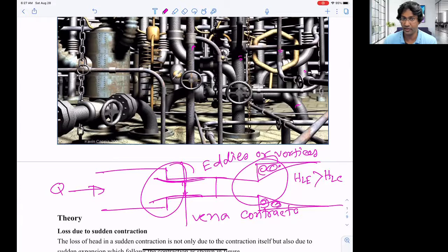due to friction, because you have to check if the flow is laminar or turbulent. Most of the pipe flow will be turbulent. So for turbulent flow, you have to know the material of the pipe, and from that you can check the table where, from research and different experiments, people have already found the exact roughness for literally every material. So you can use that value, the friction factor f, in order to calculate your major loss. So you can consider only your major loss, right?